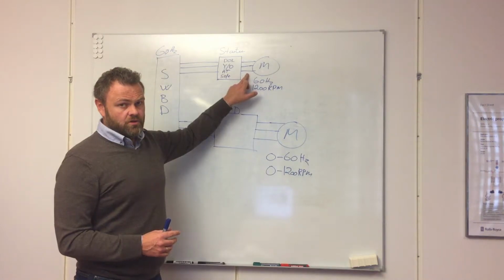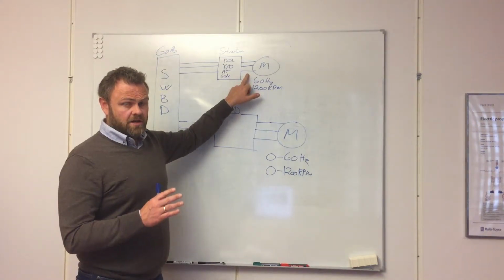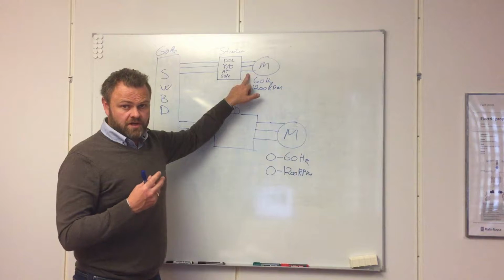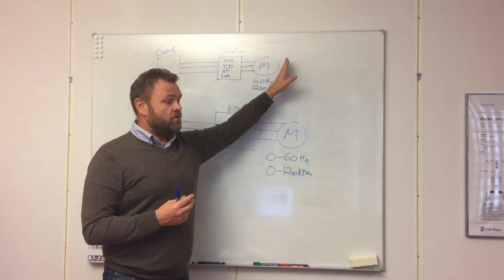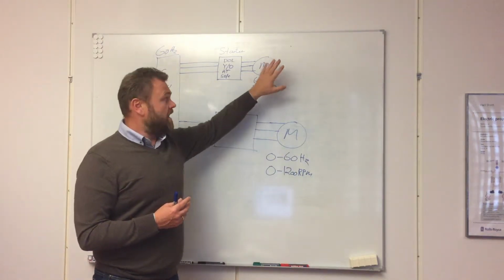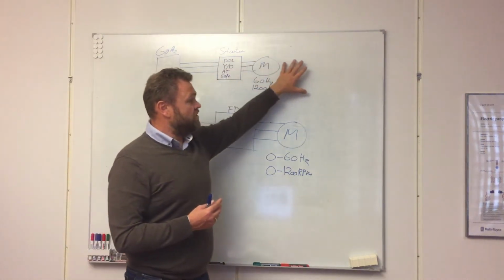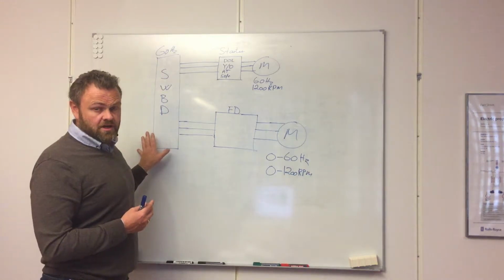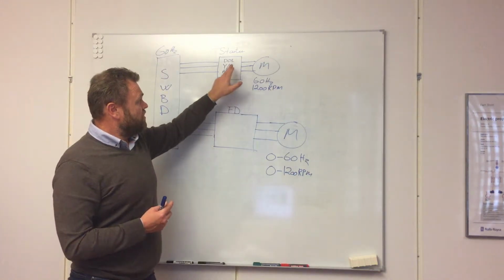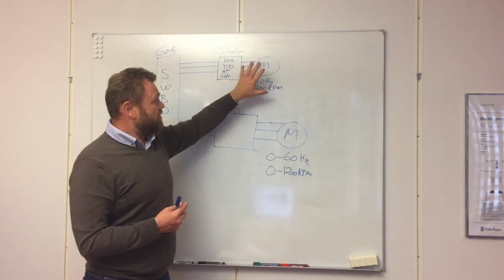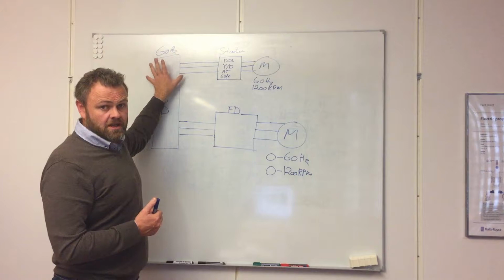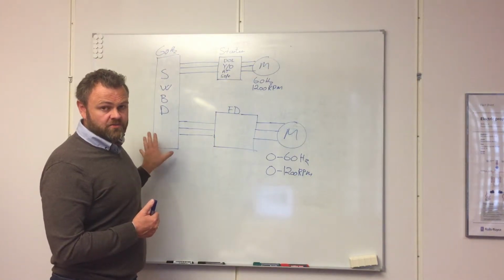With this one, you do not have a lot of torque through the start sequence, so you need to be conscious about what equipment you intend to start and look at the complete starting device as a system together with the switchboard, because once you push the start button on a big motor, you will influence the voltage on the switchboard as well.